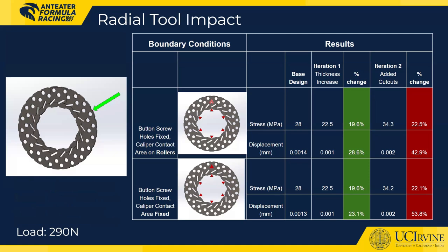The results indicated that increasing thickness reduced stress approximately by 20%, while displacement improved by up to 28%, while adding the cutouts increased both the stress and displacement. This suggests that a slightly thicker rotor could better withstand accidental tool contact.